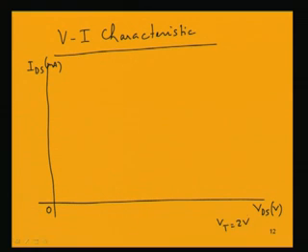So, if Vt is 2 volt, that means for gate to source voltage less than 2 volt there will be no current flow. So, we have say these are 5, 10, 15, 20 etc. voltages, and here we have 1, 2, these are the current magnitudes in milliampere.